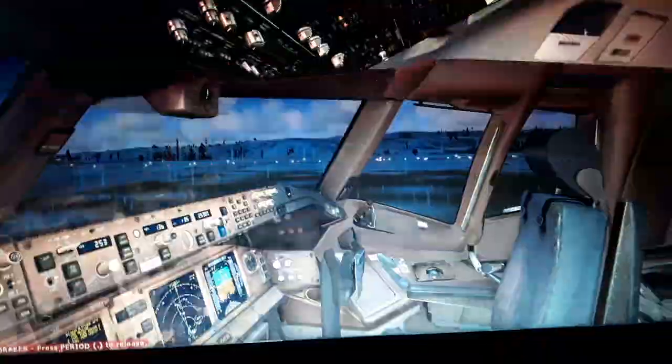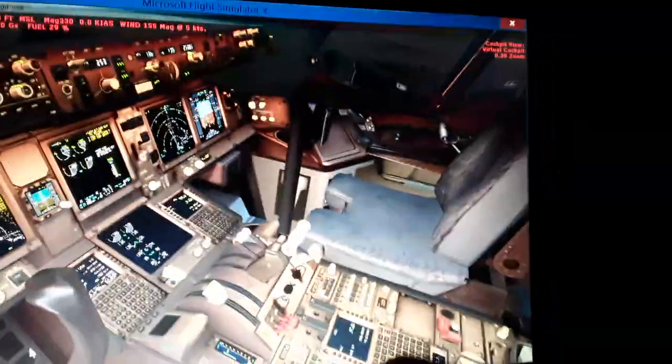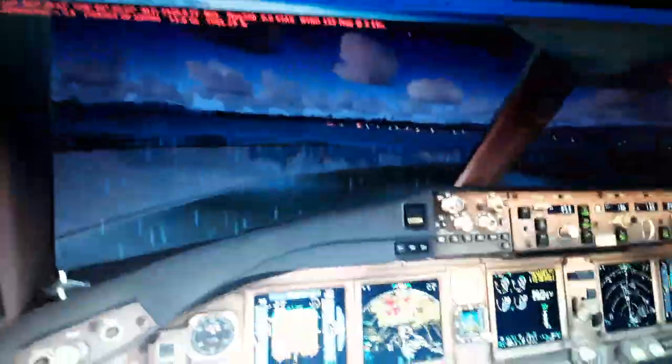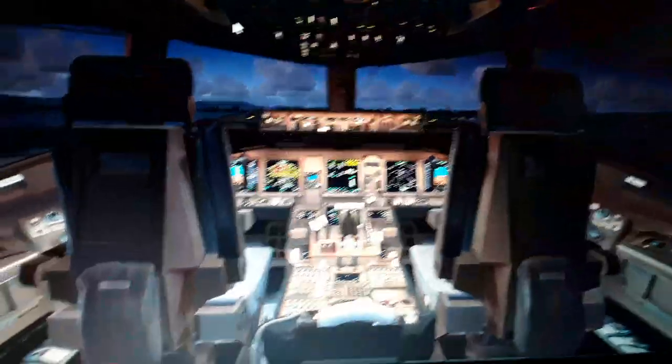The overhead panel will go very quickly, and we have to proceed for the takeoff after the overhead panel finish. So I will show you a couple of things here in the overhead panel, some systems. So you can see this is used for maintenance in the ground, disconnect fluid, hydraulic fluid, the circuit breakers also for maintenance, only reset in flight.